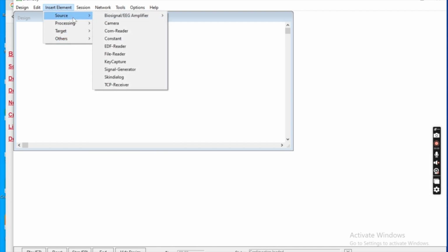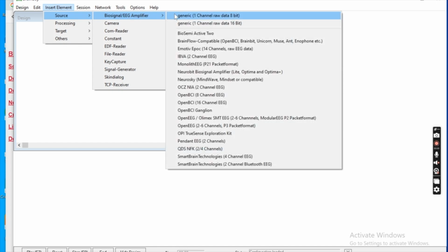But first of all, we're going to set up a sample algorithm which would be designed to read EEG wavebands at this stage. So that's the 1 to 30 hertz range, and obviously depending on the biofeedback signal you're looking to capture, just go and look up what waveband you should be tuning into, and then you can use your filters to set up your own algorithm for that application. But for now, we'll just set up this sample one to be able to read the standard EEG signals.